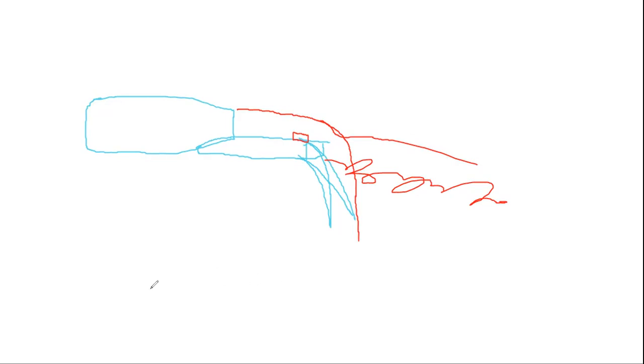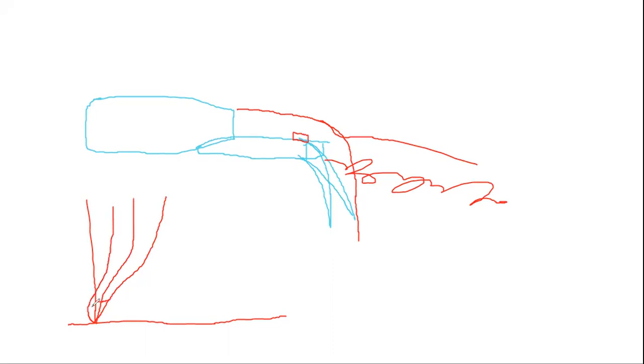What about the principle of working? Look at this. This is the surface, and this is the speed profile of the boundary layer. And when there is a drop in speed near the surface, like this, or a reverse flow. Reverse flow is a separation. So there is a big speed, small speed, zero speed, and reverse speed. And when you have reverse speed in the boundary layer, it's a separation case.